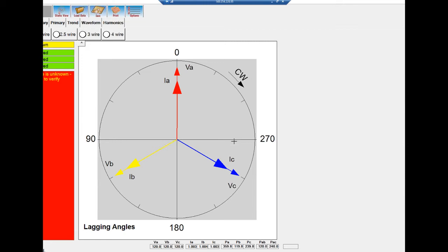So now I've grabbed a little clamp probe I have here in the office. You can plug a probe into the RW and instead read from the probe while in power quality. You can plug it into any phase and it will read current for that phase. So I'm going to plug it into A phase here in a second, go over to my primary, and we should be seeing 20 amps on IA down there at the bottom for metrics. I'm going to go plug that in right now.